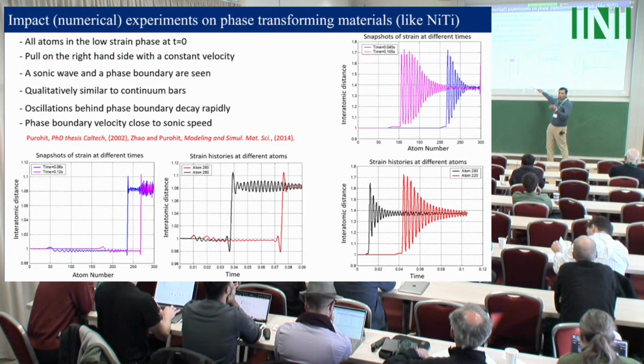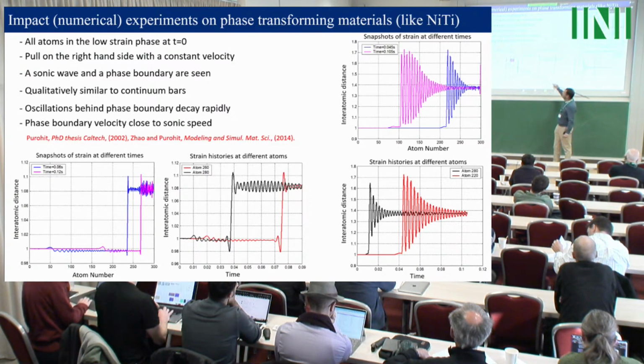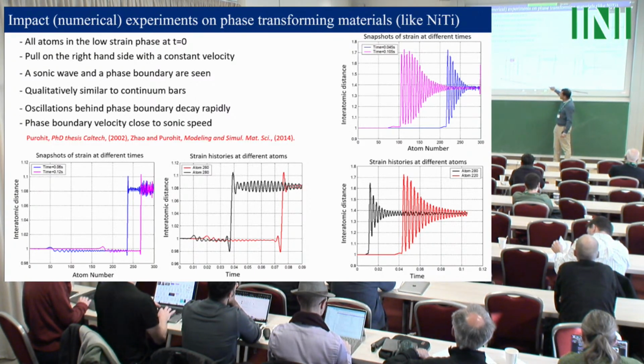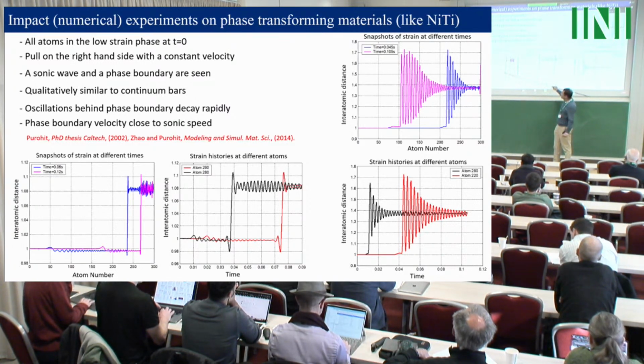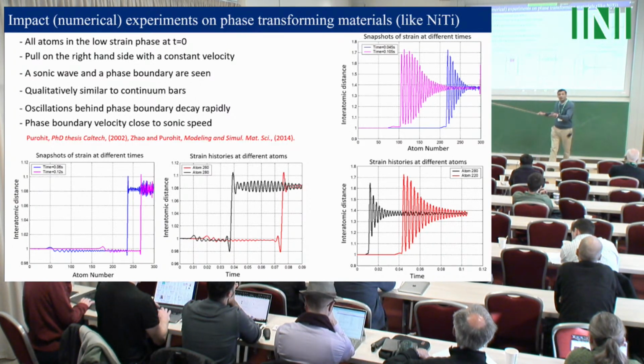When you view this problem at the continuum scale, you can write down the driving force across these phase transition fronts in terms of the strain behind and ahead of the front. From the atomistic or discrete calculations, you know exactly what the speed of these fronts is as well. So these calculations are implying a kinetic relation, and that kinetic relation can be used to solve other problems.